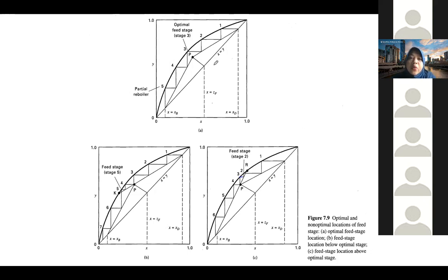In practice, getting more stages is very difficult. We can't just shut down the plant and change the distillation column. It's really not practical. So sometimes we need to change the reflux ratio, or the composition, or the amount of distillate that we can get. Sometimes that is the play around.